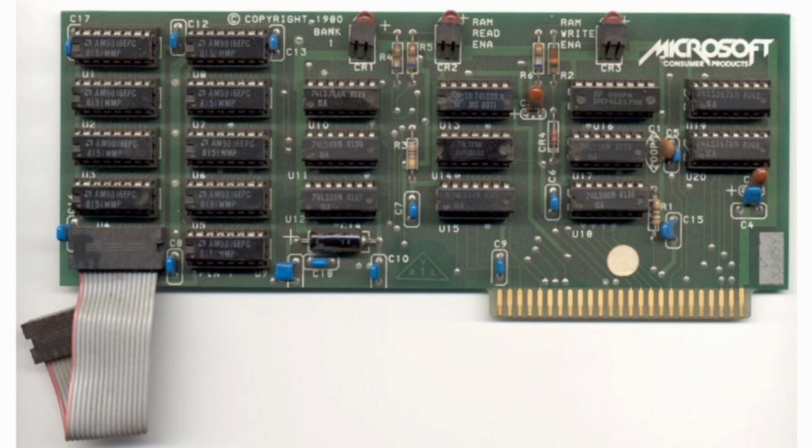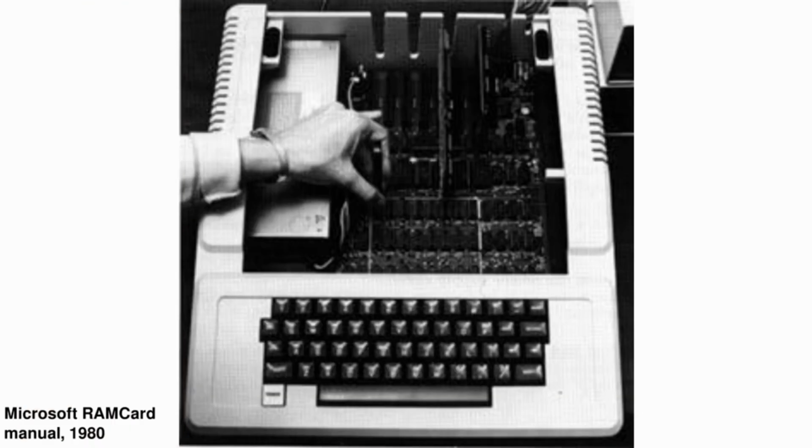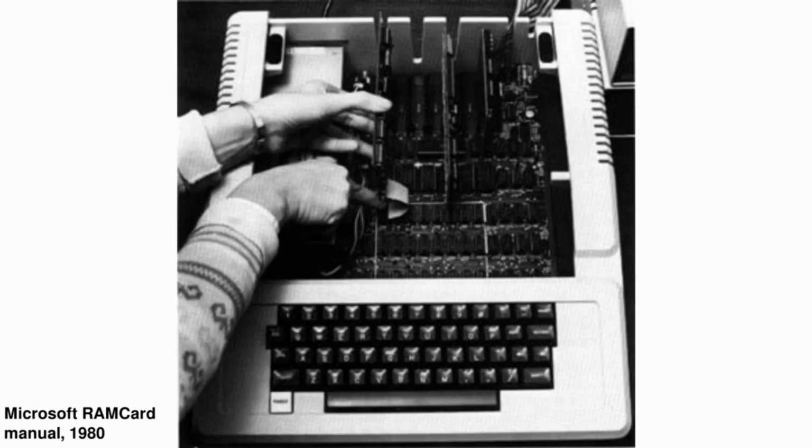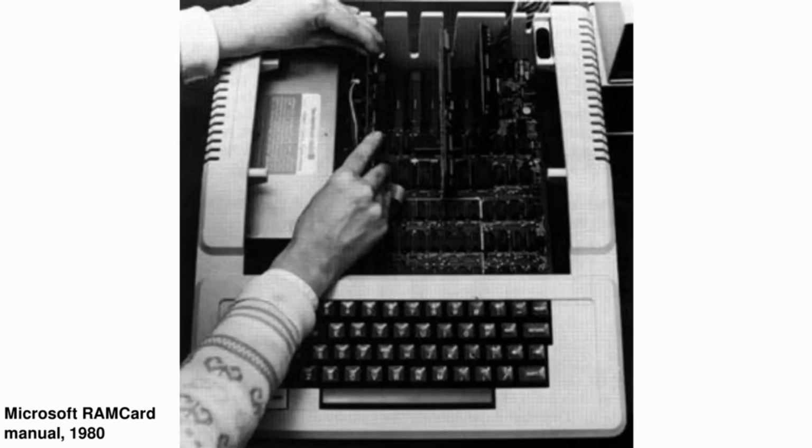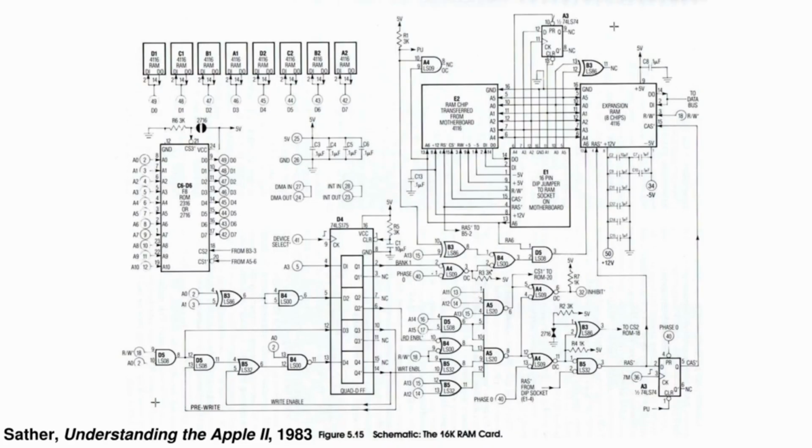Another notable aspect of the Apple II 16K cards was how they were installed. Note the pigtail in the lower left corner of the card. To install a 16K card, you had to remove one of the DRAM chips on the motherboard, plug in the 16-pin jumper in its place, and then install the removed chip on the card. This was a trick to save hardware. While the multiplexed addresses needed by the DRAMs could be generated from the addresses on the slots, it was much cheaper to simply steal these signals directly from the existing DRAMs.